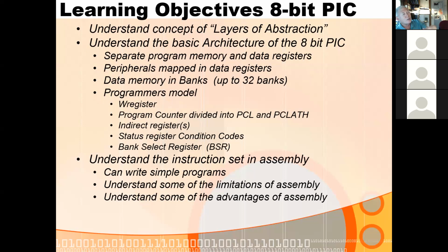But the problem is, once that lower 8 rolls over, it's not going to automatically increment the upper 8. So you have to make sure that your lower byte isn't FF. When you add one more to it, it will go to 00, and you should increment the upper 8 bits. And if you don't do that... but the good news is there are instructions that take care of this automatically for you as well. So you don't even have to worry about this.